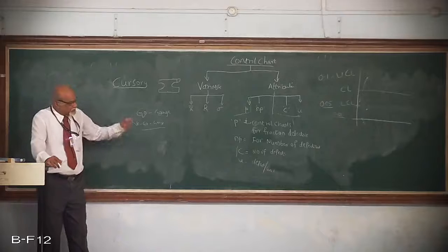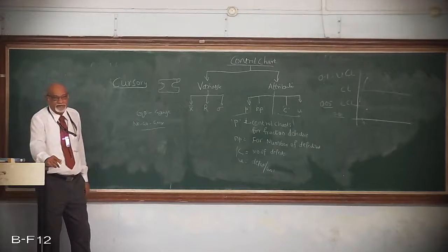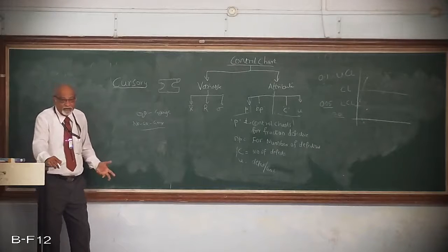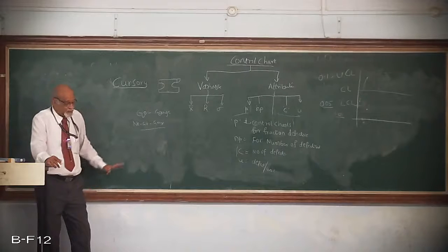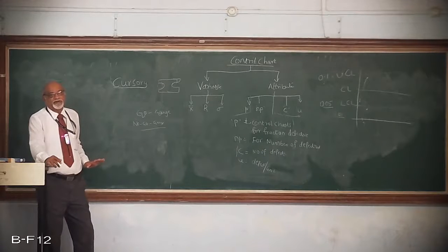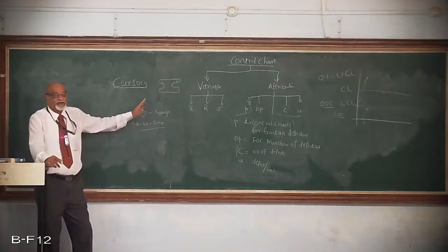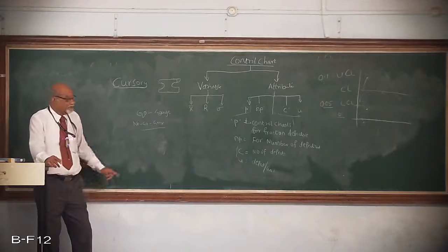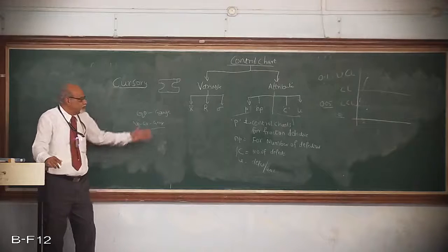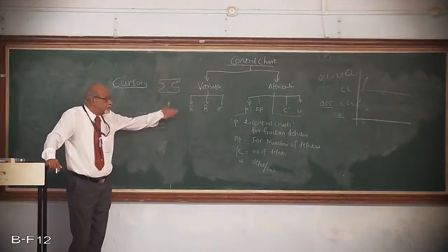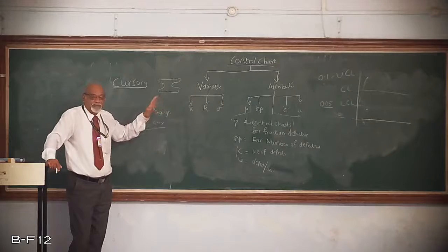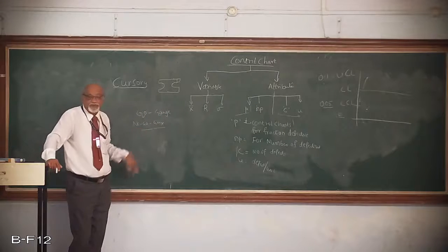That is how they will start with P chart. They can classify it as defective or non-defective. How much defective, I will not tell. Actual measurement only will tell what is happening. So that is what I told you. First they will go for control charts for attributes, then they will go for control charts for variables. Okay?